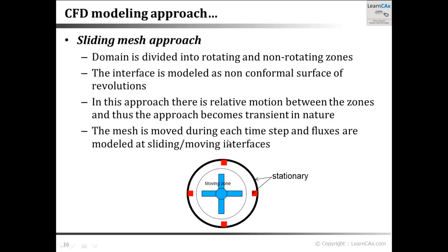The mesh is moved during each time instant or step, and the fluxes that are calculated because of the flow as well as the motion are modeled at the sliding or moving interface. This interface, the dotted line you are seeing, is the sliding or moving interface.